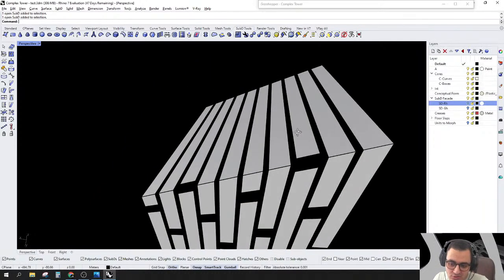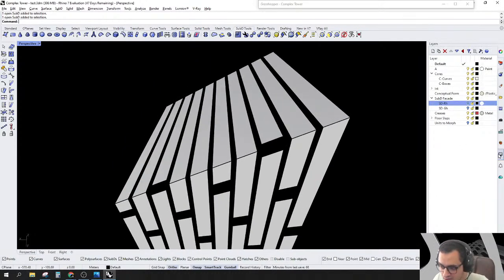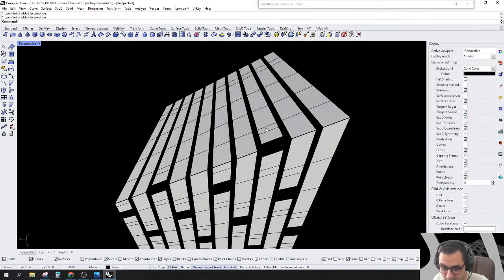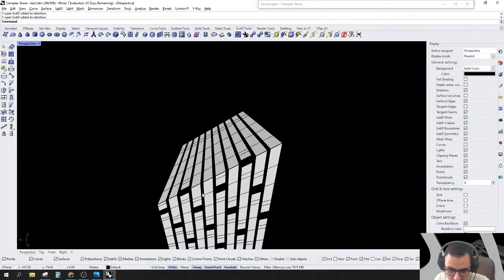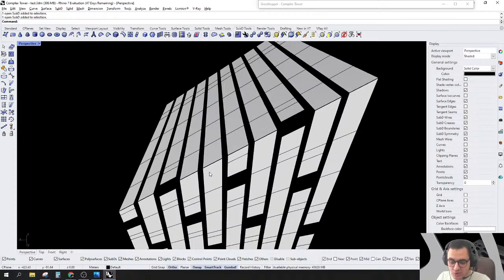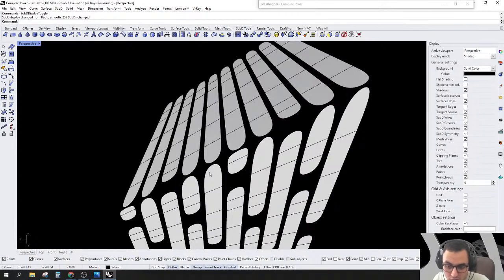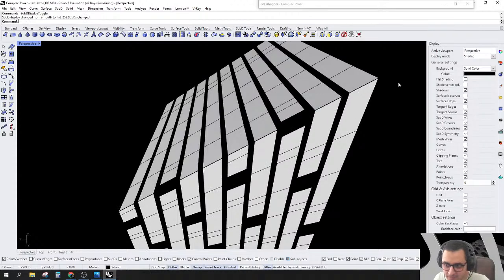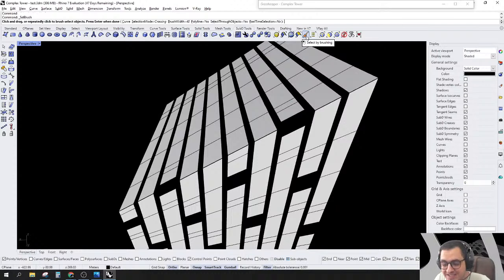So what I really need to do right now, in here, I need just to see the sub-D wires. So I will not select any unnecessary vertices. Make sure that you are working in the smooth mode, especially when you are selecting vertices like this, because it will be harder to know where the vertices are. So hit tab, and when you are in the vertex mode, go to the brush. The brush is a magical command.